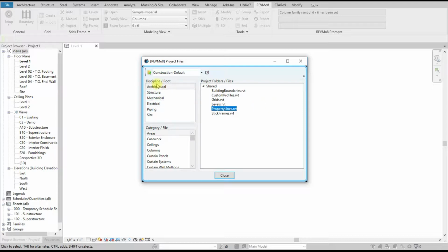And so these are the disciplines. You can add your own files. You have default disciplines, architectural and structural, and each one will have proposed file names. If you want to add them, you can highlight it here and right click, and you have options. You can add, create, or you can drag and drop like this, and you can go to columns.